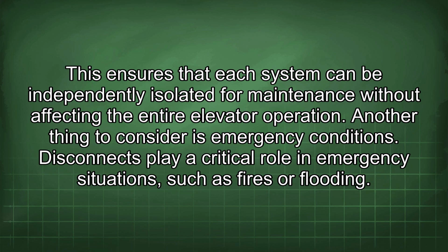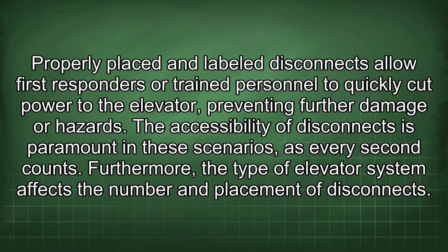Another thing to consider is emergency conditions. Disconnects play a critical role in emergency situations such as fires or flooding. Properly placed and labeled disconnects allow first responders or trained personnel to quickly cut power to the elevator, preventing further damage or hazards. The accessibility of disconnects is paramount in these scenarios, as every second counts.